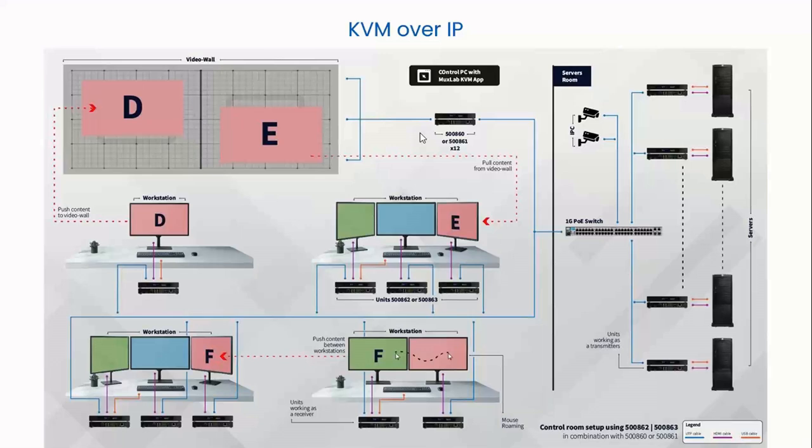So on this video wall, I can show source material from the AV over IP environment, from the transmitters and the various sources connected to the seamless AV over IP receiver transmitter switch. I can also have IP cameras supporting H.264, H.265 using RTMP, RTSP to be able to send content to the receiver shown up on the screen.